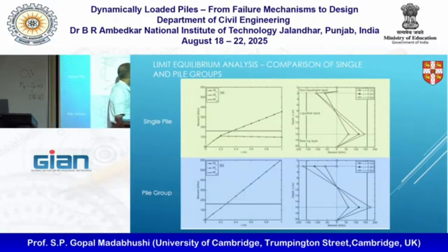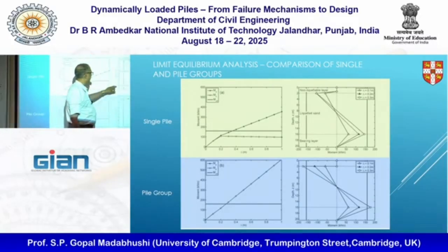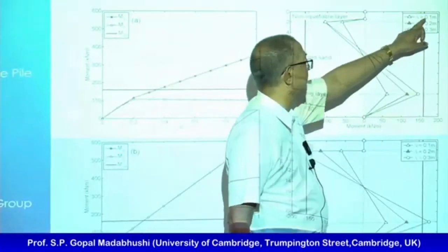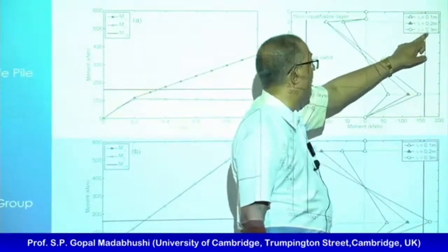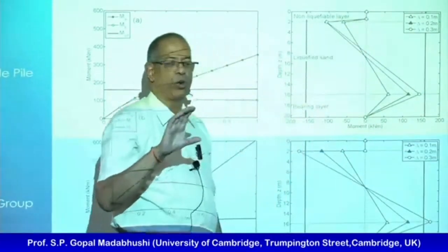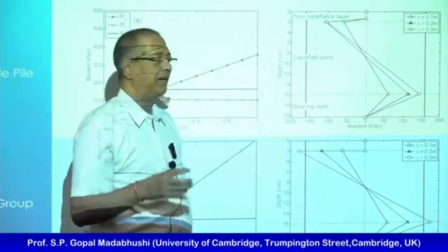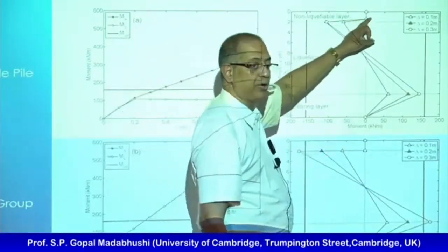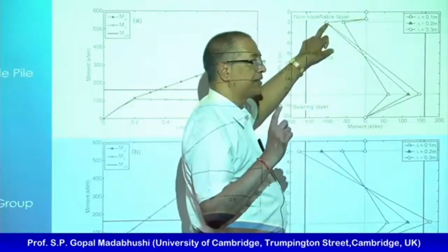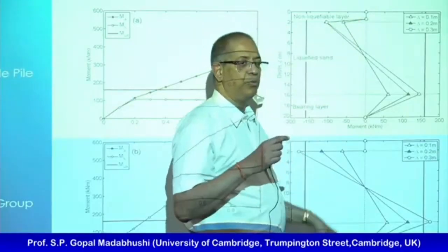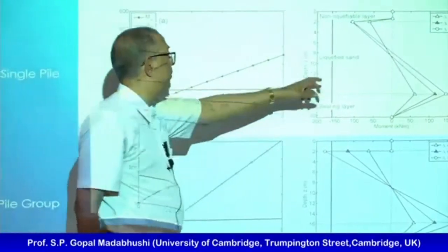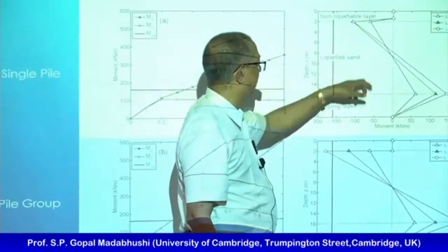So if I were to look at the bending moment distribution for different amounts of deflection, 0.1, 0.2, 0.3, you can plot this. Because the pile cap is so rigid, there's pretty much zero bending moment there. But the pile will have some moment, which is my MA being applied, and that obviously is increasing with deflections.